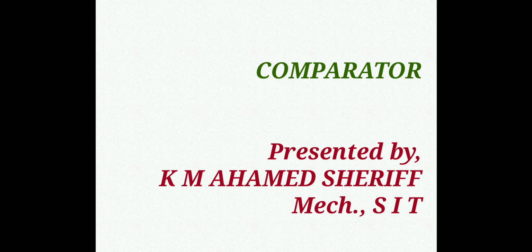A comparator is an instrument used to measure diameters and lengths on components by using slip gauges as standards. In other words, a comparator is a device which compares the unknown dimension of a part with some standard, known, or master setting which represents the basic size.